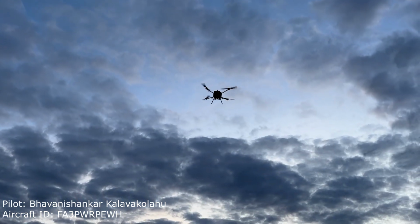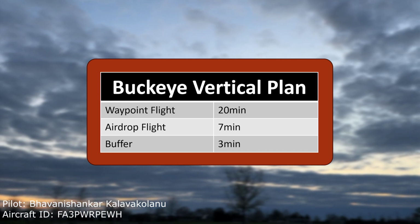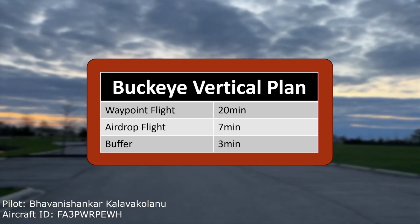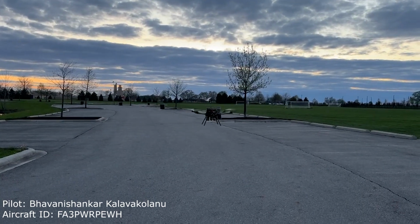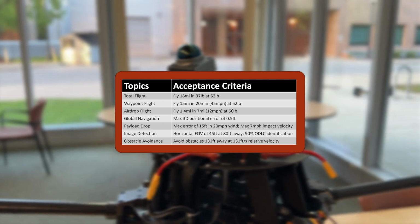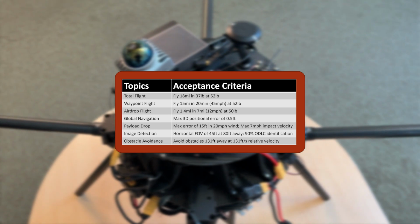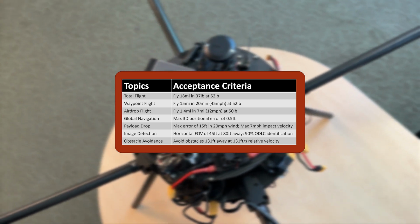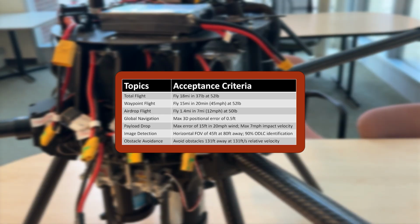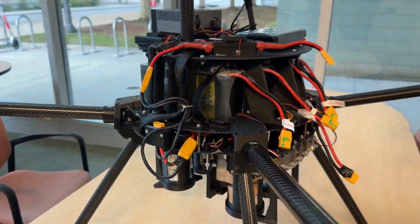To save time, the team chose not to have a refuel stage, which sets the requirement that our drone should be able to fly at least 15 miles for the 10 required waypoints in under a 30-minute time span. With this in mind, we found that a flight speed of around 18 to 22 meters per second would be ideal and that our battery life should be around 40 minutes at cruising speeds. These parameters were found after taking into account payload drops and were used along with numbers like weight in the worst case scenario to calculate thresholds for motor prop configurations as shown later on in this video.